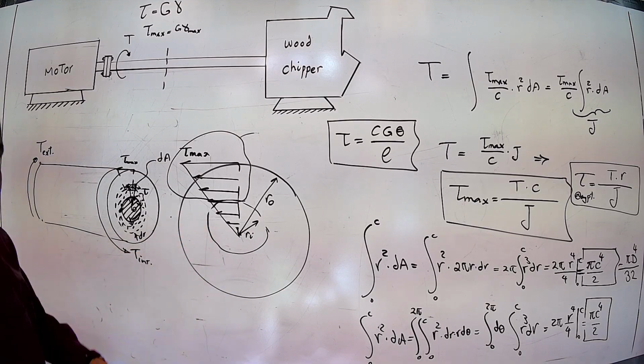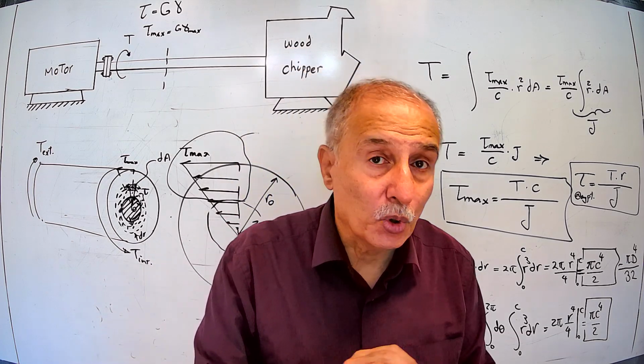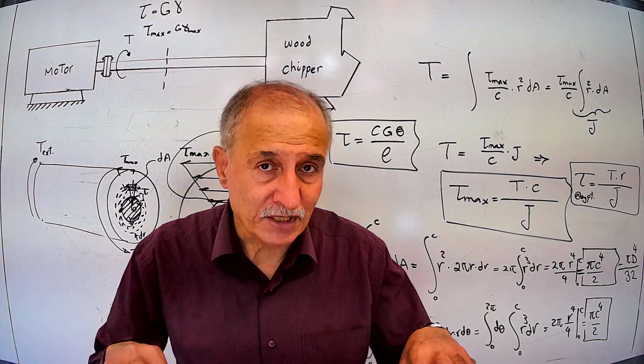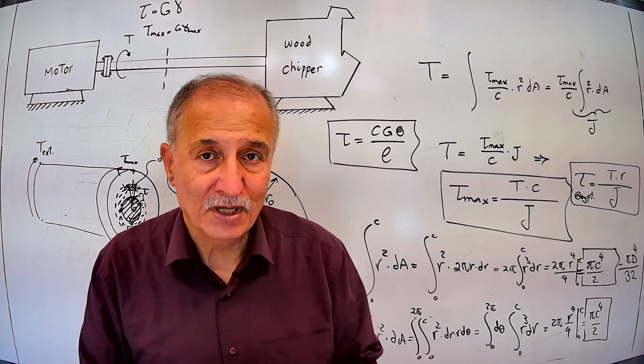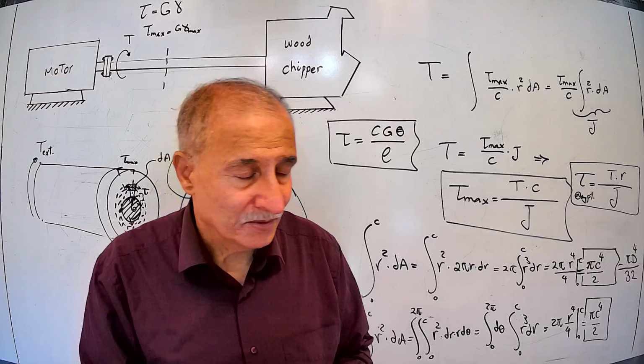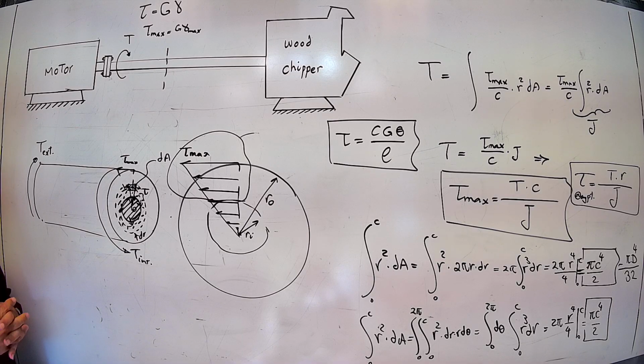This holds only when the shaft is transmitting torque only. If there is bending, the story will be different. For bending, we need the material in the center as well. For transverse shear load, we also need the material at the center. Then, this is the story of a prismatic circular cross-section shaft, of an elastic, Hooke's law obeying, isotropic material, subjected to torque.